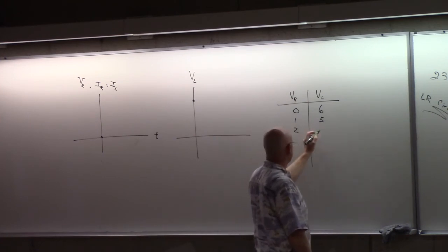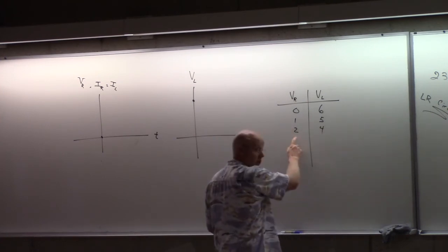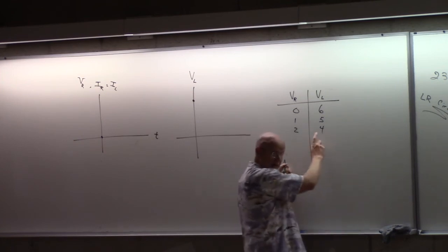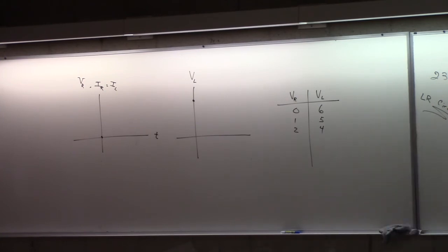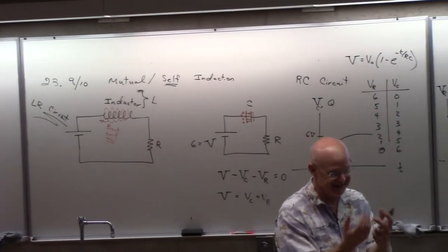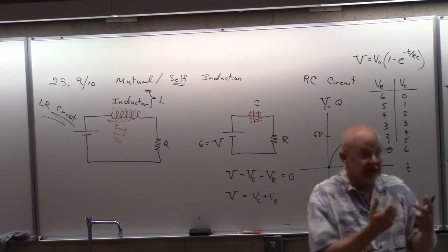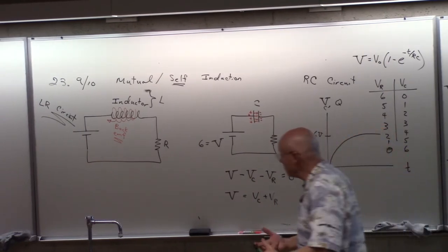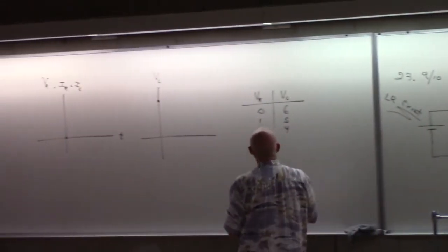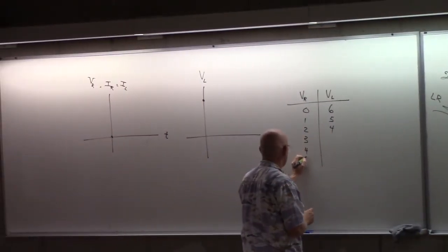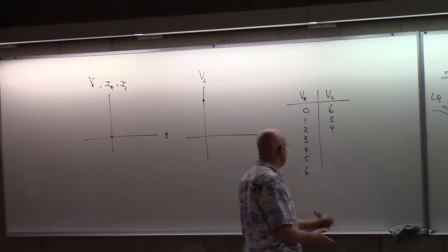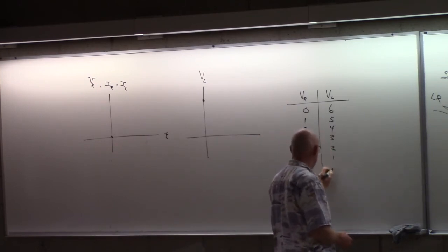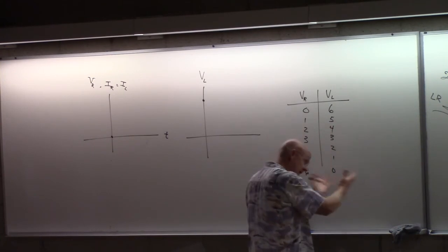And so we're going to constantly increase the current. That's the whole reason you're making a voltage here. Remember, you can only get a back EMF when there's a change in the flux. The change in flux can only come because it's changing within itself. And it's only changing within itself because the current is changing. So the current has to constantly be changing. And so as it's constantly changing and it's constantly getting bigger and bigger, the voltage on the resistor is going to get constantly bigger. Which means the stuff that's left over is for the inductor, because the total has to add to 6.